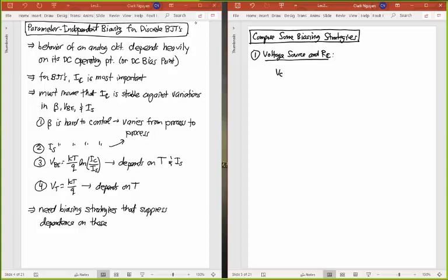And so that says I have a VCC. To bias this up, I'm going to put a VCC up on the circuit. This is the battery that I'm using, my power supply. And I'm going to send this VCC through that collector resistor, which I'm calling RC. And I have my transistor down here, right below that. And I'll let my emitter go to ground. And I'm just going to put a voltage source, VBB, at the input. That will set the voltage at the base.